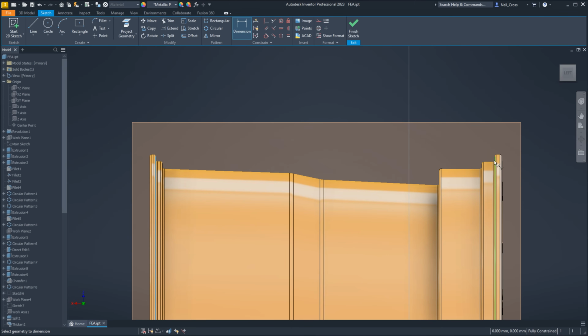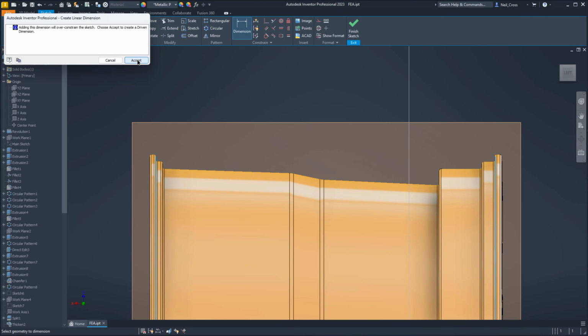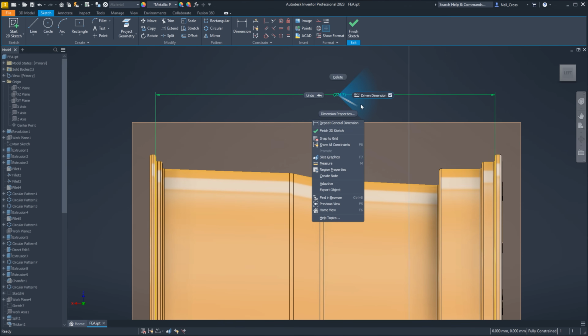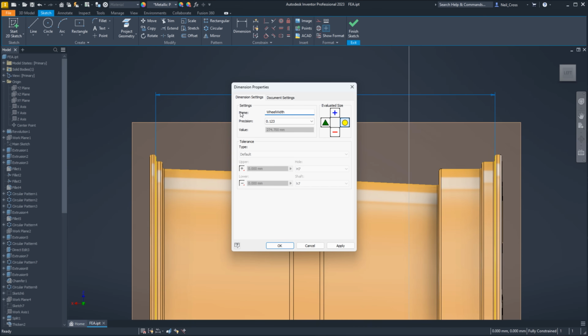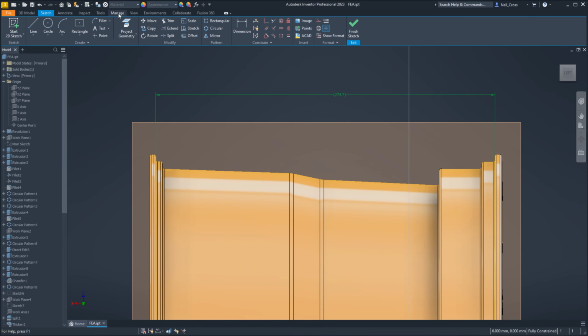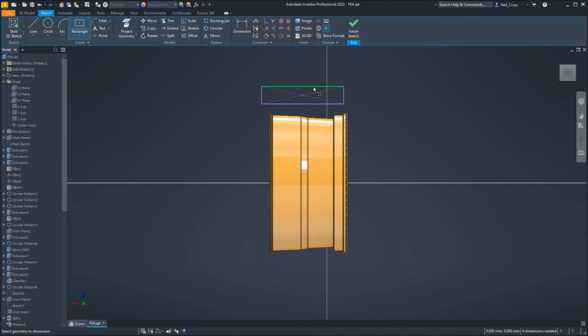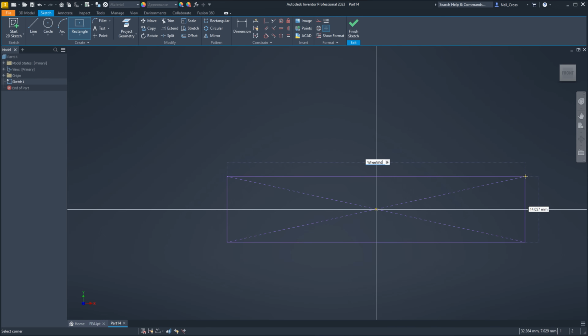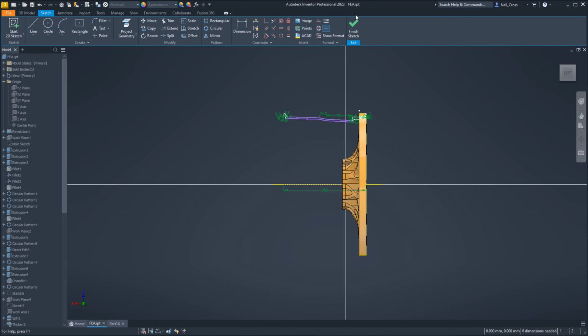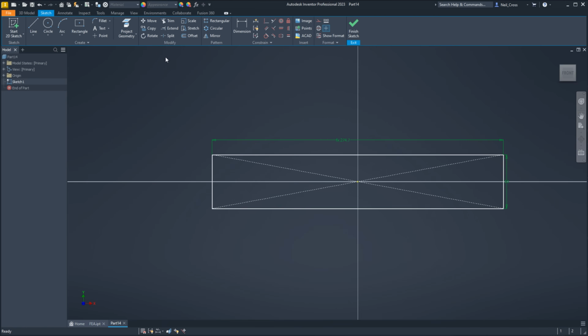But in Fusion 360, due to the way they've built the sketching architecture from very early days, you just can't do it. Well, you can reference a driven dimension if it's in the same sketch, but in Inventor, you can create an entire sketch full of driven dimensions, set them as named parameters, and then reference them throughout the entire design. In fact, in Inventor, you can even reference driven dimensions across into completely independent different part files as linked parameters. You can build an entire part of driven dimensions like a skeletal model and link it into different parts.